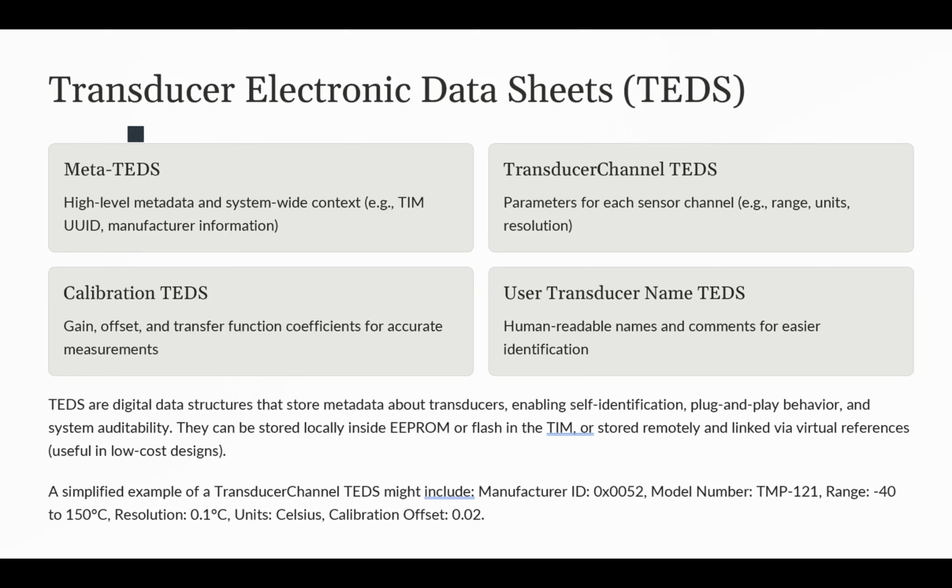Now, the TEDs, as we said, are a digital metadata structure for each transducer, which basically makes each sensor and actuator able to describe itself automatically to the system. So we have self-identification capability, and we have plug and play capability.